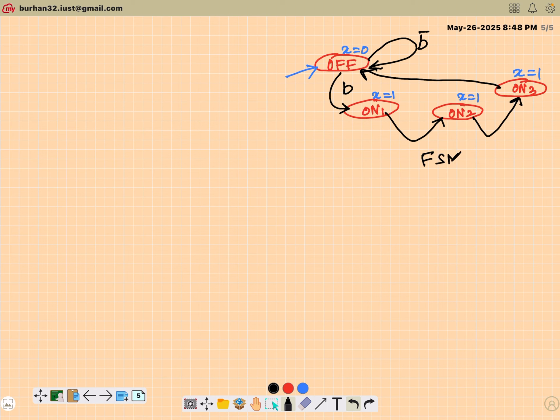It has all the characteristics of a finite state machine. There are a finite number of states. So maybe I should summarize here that the number of states is equivalent to 4. Right? Then there is an initial state as defined by this arrow. Every state has an output given, and we have complete information about, if I am in a current state, how I can move to the next state. So the first step, which is capturing the finite state machine, is done.